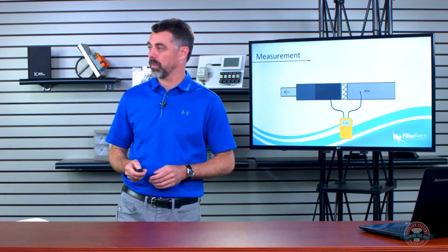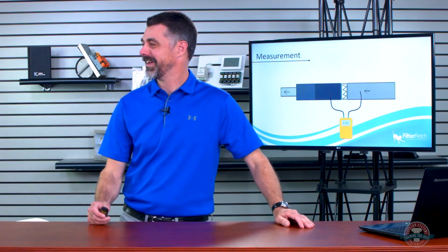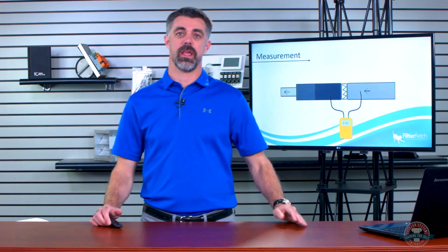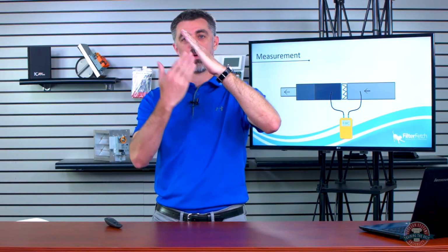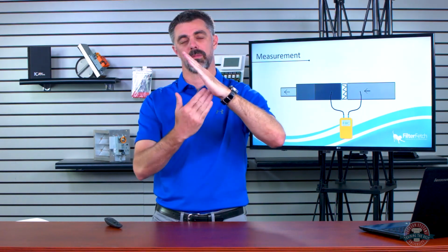I got another one, from a different Robert. He wants to know: most apartments have slanted evap coils built up in the wall, and there's no way for air to come straight in. How do you overcome that? So, slanted evap coils in apartment units, you want it as straight as possible. You can't always get it. It depends on the installation, and on how the filter rack is installed. I like to have as big a filter as possible. And if you have a slanted filter rack and the air is coming straight up into this, I want the pleats running this direction, right? Not necessarily across that. And we're going to talk about that here in a minute.